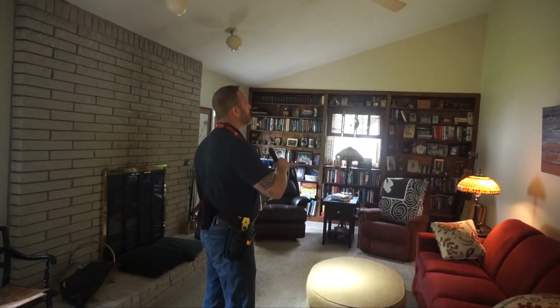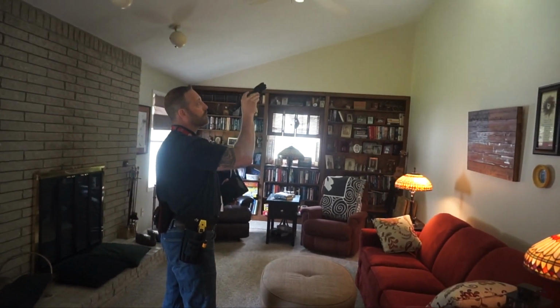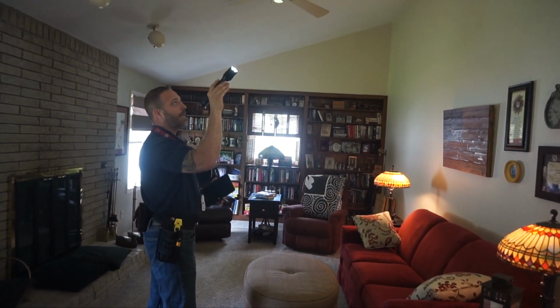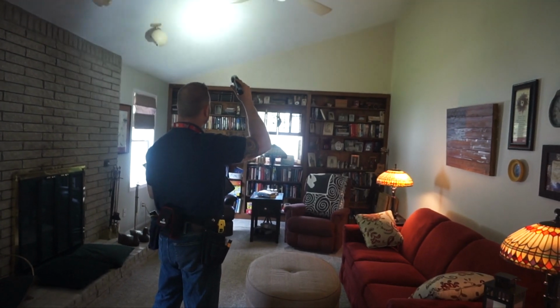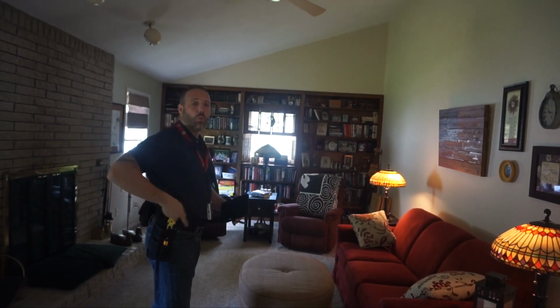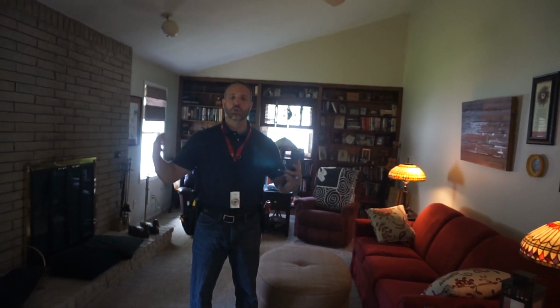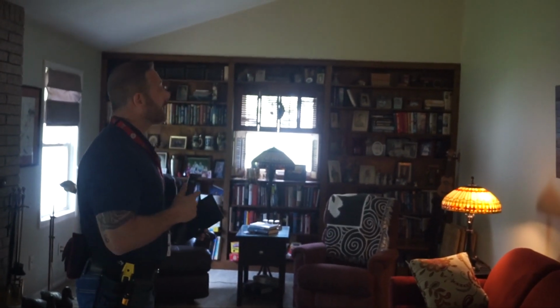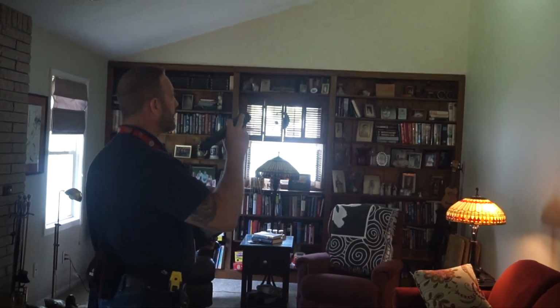So let's get started. The first thing I do is, again, we take out the flashlight and we're going to be looking at all the joints between the ceiling and the wall. And what we're specifically looking for is water stains. When it comes to a general interior inspection, we're trying to see how the elements of the weather are infiltrating the actual building itself.